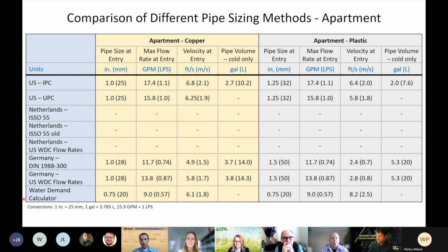So once you've designed your system, you could run hydraulic models and find out how often it does occur and how often you potentially could have too large a velocity, too large a pressure drop. Probably this gives extra room for going to a little bit smaller pipes even.